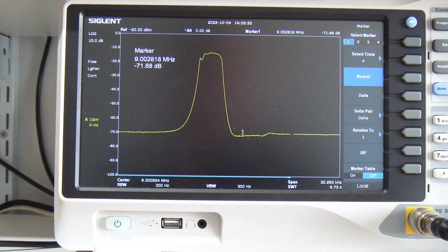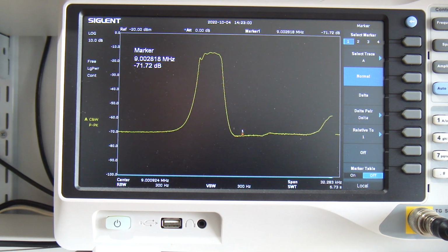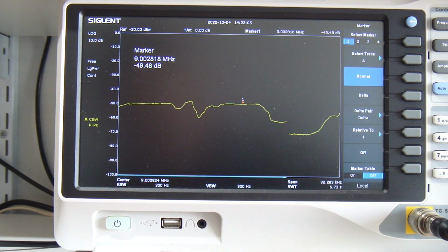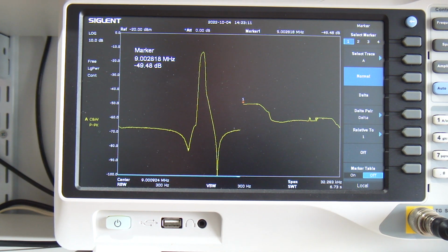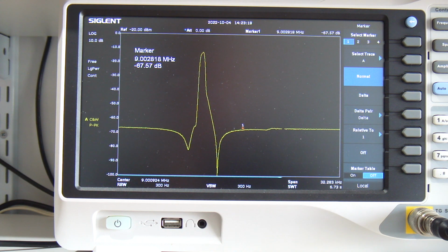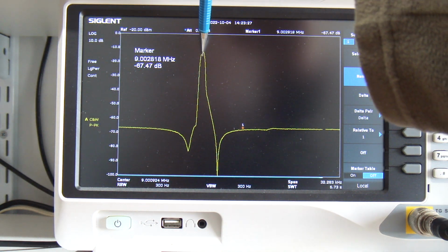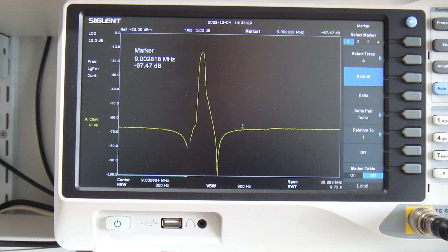And as you'll see later on, now that I know that, I can then work out what the turns ratio needs to be for the two IF amplifiers. If I was now just to move across to the CW filter, let me just change that to there and change that to there. So this is the CW. This has a bandwidth of 560 hertz, so I think that's quite good. I don't really want to go a lot lower than that, so I think that's quite fine. So I will give that one a go, and if we can get our CW signal to be in there, then we're looking pretty good. So yeah, happy with that.